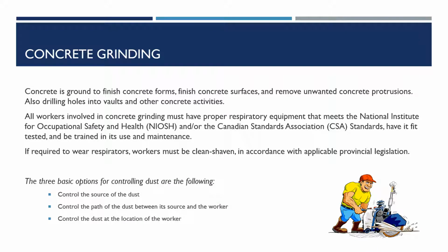Concrete grinding. Concrete is ground to finish concrete forms, finish concrete surfaces, and remove unwanted concrete protrusions. Also, drilling holes into vaults and other concrete activities. All workers involved in concrete grinding must have proper respiratory equipment that meets the National Institute for Occupational Safety and Health and/or Canadian Standards Association standards, have it fit tested, and be trained in its use and maintenance. If required to wear respirators, workers must be clean-shaven in accordance with applicable provincial legislation.